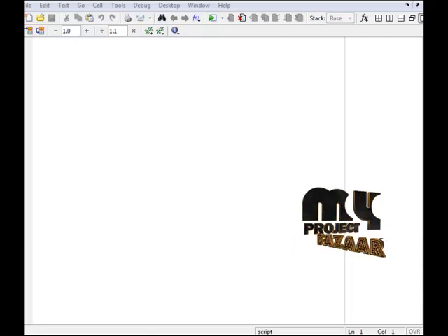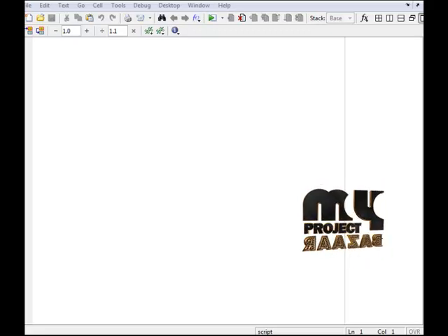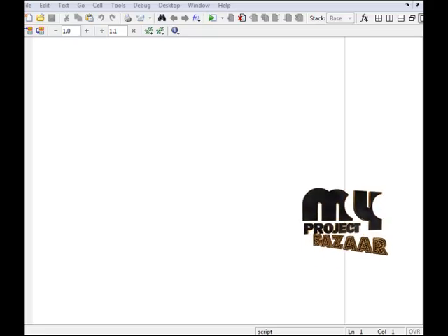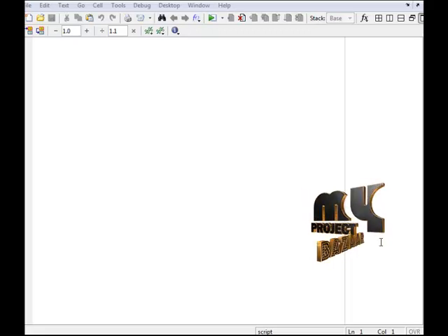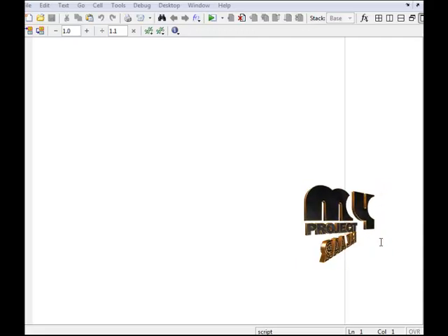First, in this process, we design the wind turbine model, that is the turbine DFIG model, the doubly fed induction generator. Then from that DFIG model, the result is going to the SVC, that is the static VAR compensator. Next we apply the fault in this circuit, that is on the transmission side, then we have to overcome the fault, so we use the three-phase circuit breaker. The next process is going to the PV panel, so we design a separate model for the PV panel.